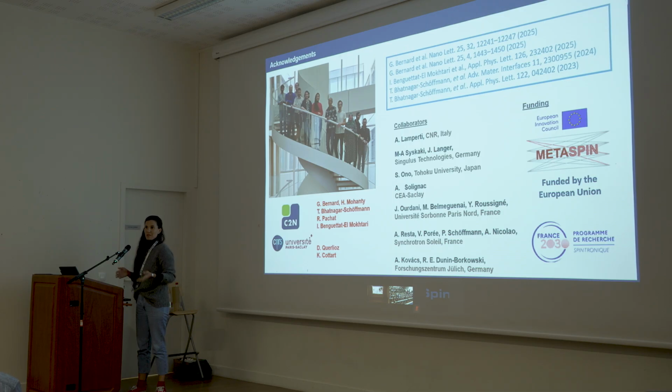We wanted it to be transparent so we could do microscopy, the kind of things that I showed today. So it's a compromise between conductivity and transparency. It's relatively conductive, so it can be an electrical contact, and it's decently transparent so that we can see the domains through it. Sometimes we have to watch out because the contrast is inverted or there is some strange optical effect, but we can see very well through it.